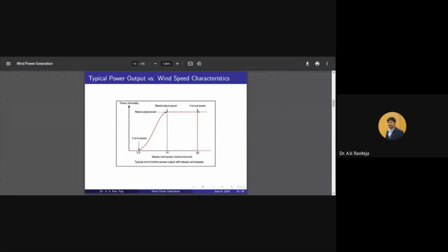When they are operating at full capacity, I cannot ask them to operate at higher than their ratings. So if, for example, the wind speed exceeds the rated wind speed, then I actually am capable of generating more power. But since my equipment have already reached their ratings, I cannot allow the turbine to rotate at higher than the rated speed. Then what should I do?